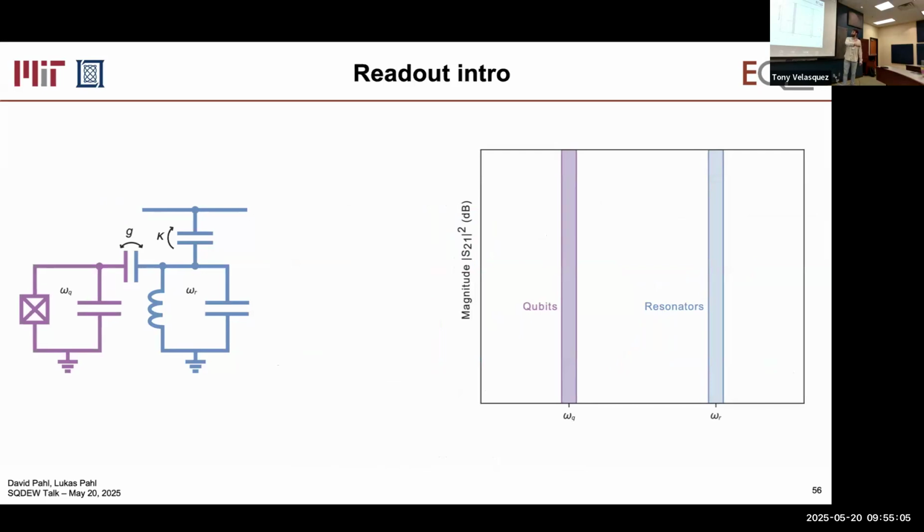If you put ports here and here, basically the path that a qubit excitation would take, then you can see that it really easily leaves if that photon is at the frequency of the resonator. That's where this resonator becomes like an open. That would be really bad if our qubit photons were at this frequency, but they're not. In fact, at this frequency, they're suppressed. They don't leave as easily.